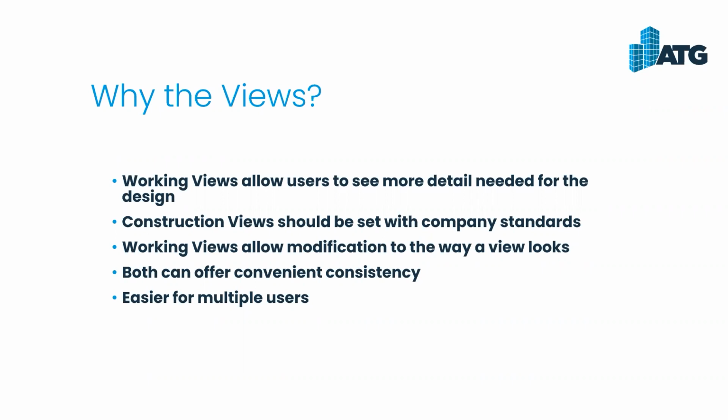We don't want people going in and changing stuff within the construction view because it looks better for me in this instance than what this other person has. We don't want to change those construction views. We want them set to the view template assigned to those different views, whether it be plans, reflected ceiling plans, elevations, or sections. Those should all have different view templates assigned to them.